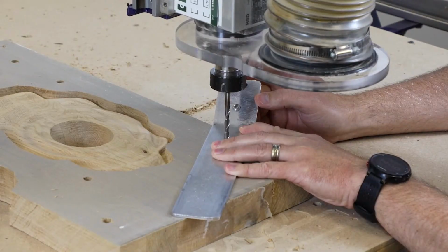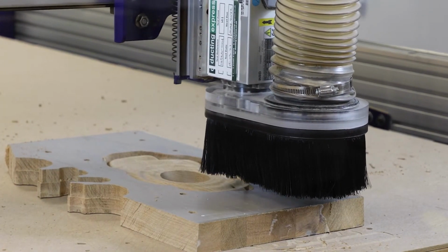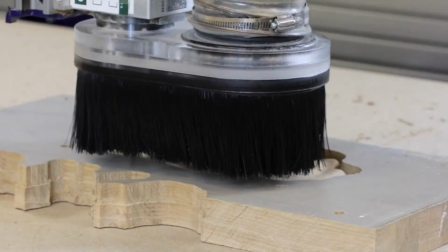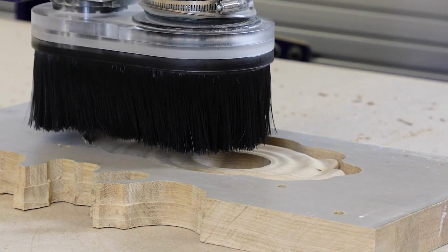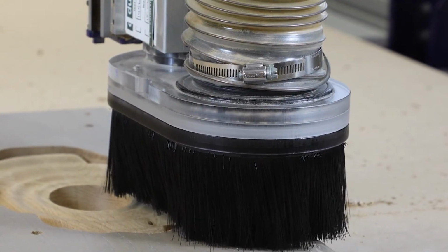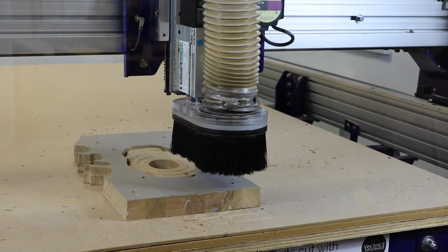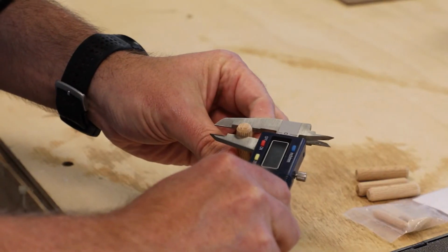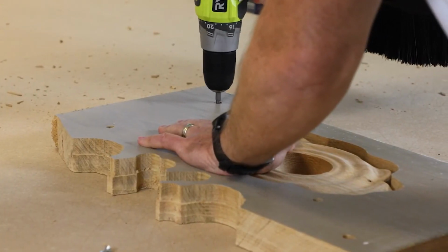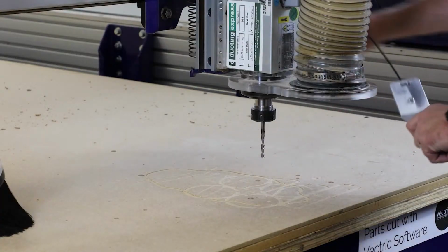Now we're going to swap back in that 1/4 inch end mill and do the cutout pass at the half depth. Again, we lined up the tabs from the front and the back so that I'd have nice thick tabs to hold this in. And then both sides are only going down about halfway in the material. So those tabs will be right in the center of the sides of this base. Had a little quick measure of my dowels, and then I went and test fitted them. Everything looks good. Really quite happy with that.